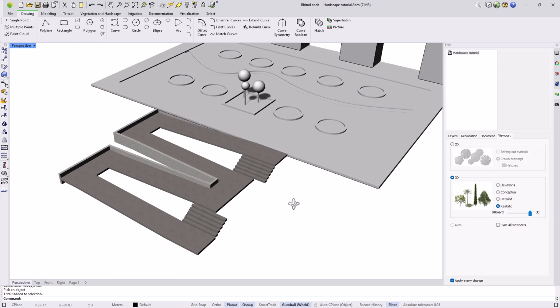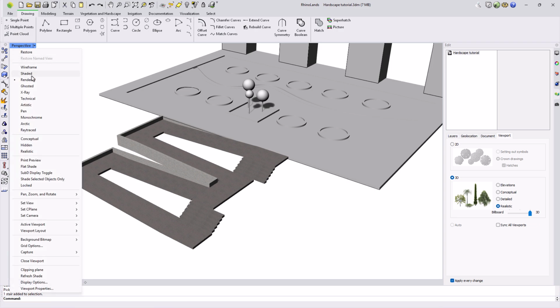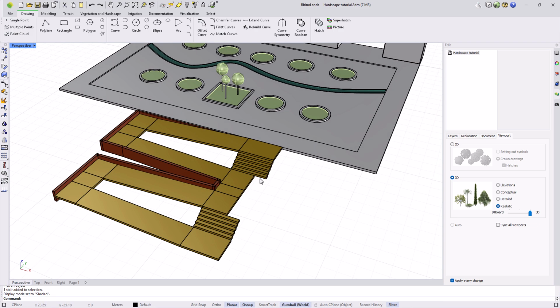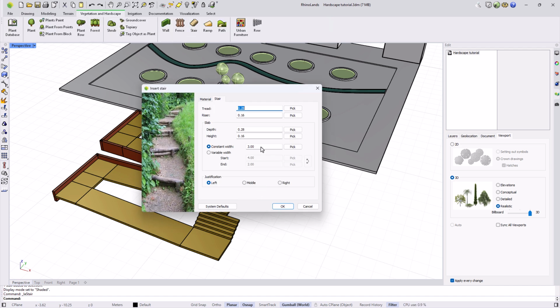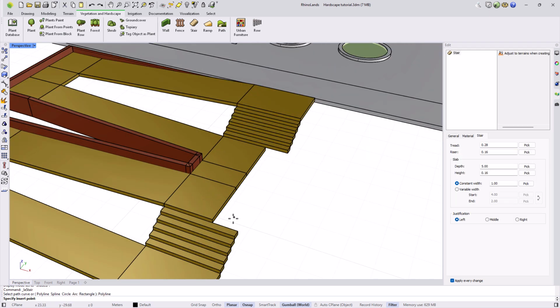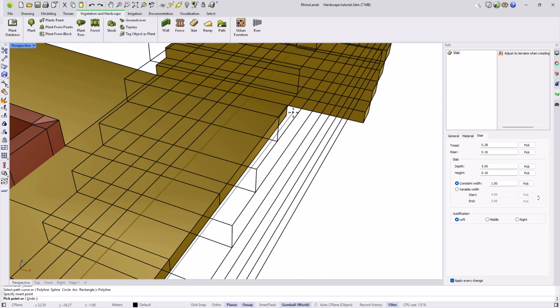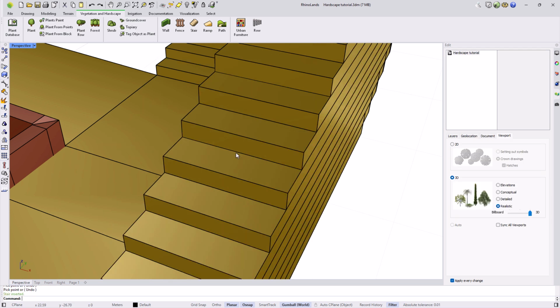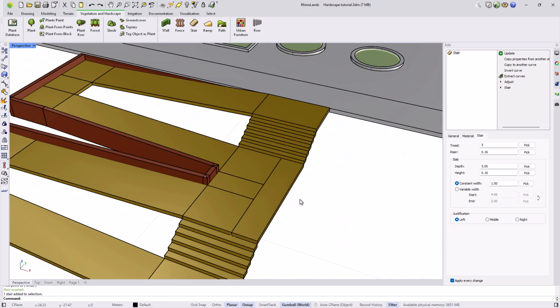Since we cannot create extensions on landings that are wider than the ramp itself, the space to cover, I can do it with a single step, with a width of 1, with a step depth of 5 meters. And I also adjust the tread value to accommodate a single slab.